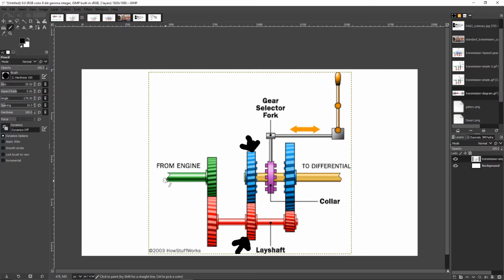We use the clutch because by disengaging the engine, it allows this gear to rotate freely, which makes it easier for the synchronizer to engage, but you don't have to have it. So when I told you guys that 18-wheeler truck drivers don't use their clutch, that's why. And that's part of what takes them so long when you're behind an 18-wheeler and he goes bop, bop, bop. It takes a second for him to find the correct wheel speed and engine RPM to line up smoothly.